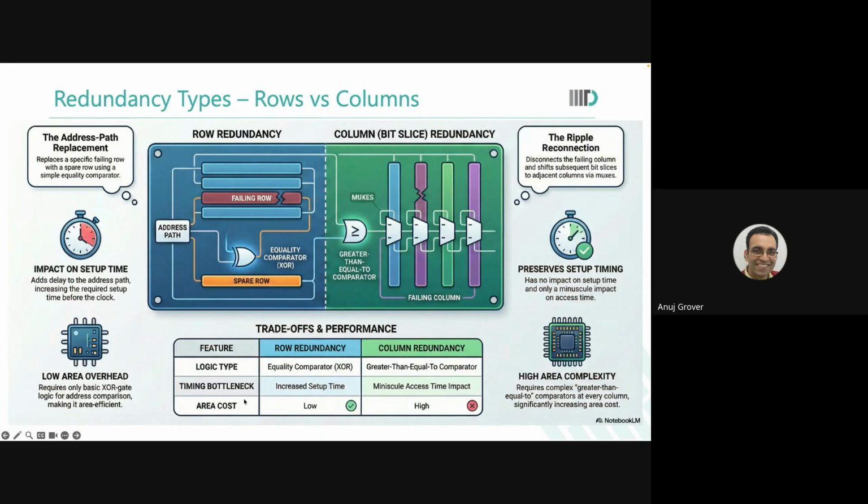I have to have extra control logic and state machines in my soft design so that it can test my memories every now and then. And if something is failing, it should also have a mechanism of triggering repair circuits and revive the chip automatically.